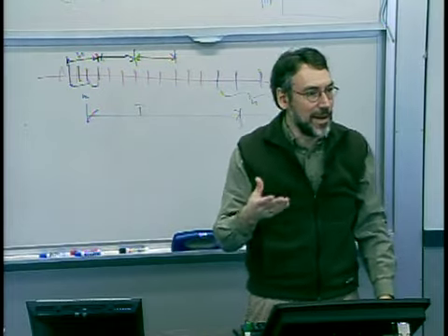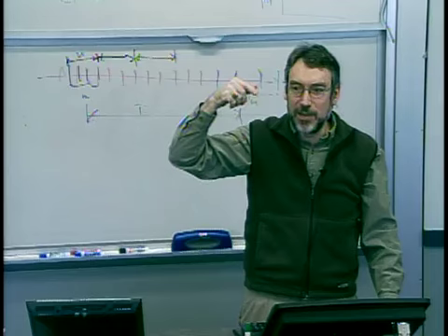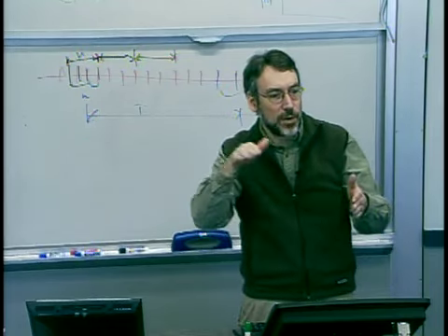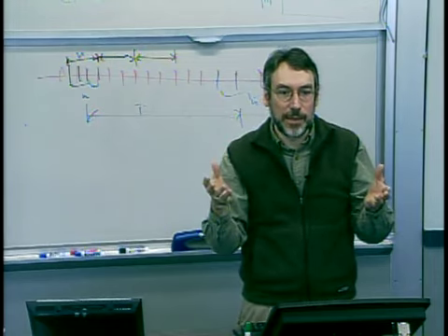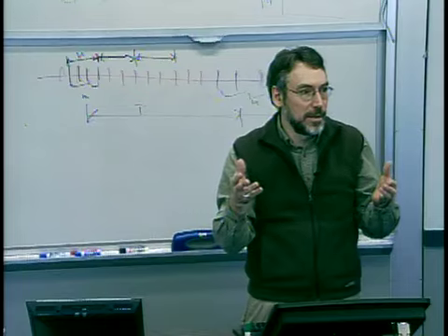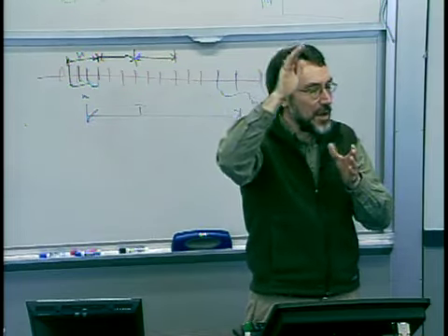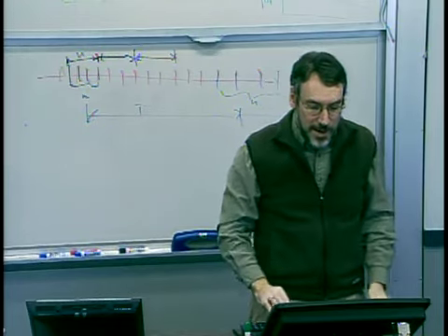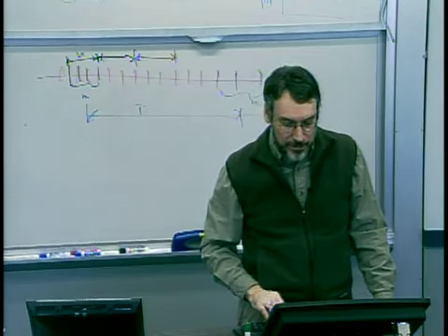Another way of looking at it is we're filtering high-frequency deviations down to try to detect a smoother average that's more indicative of the true mean of the process. I'm really not trying to detect variances. I'd just as soon have one signal that just told me how good my mean is. And so an X bar really does filtering of your data. Okay?